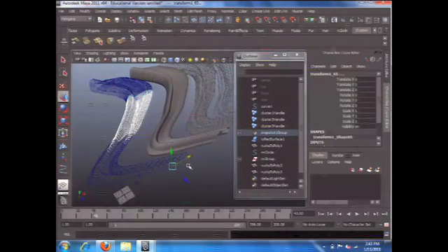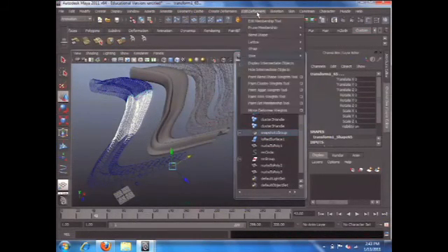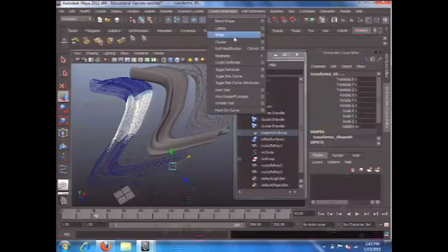Okay, so that's about morphing animation. Again, let me conclude: in this animation, I animate the cluster, right? So the cluster is changed from one location to another. You make one object morphing to another object. So that is something you have to convert that selected points into cluster, right? And then you can manipulate this morphing, this transition.